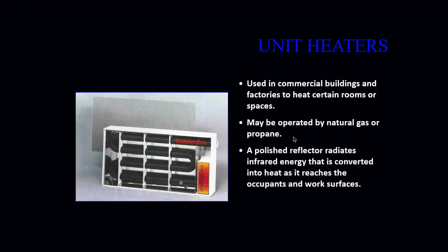Unit heaters, these guys are going to be found in a lot of your commercial buildings and factories to heat only certain rooms and spaces. Okay, they may operate either on natural gas or propane. And a polished reflector radiates the infrared energy that is converted into heat as it reaches the occupants and work surfaces. Okay, what you have here is what we call a radiant heater.